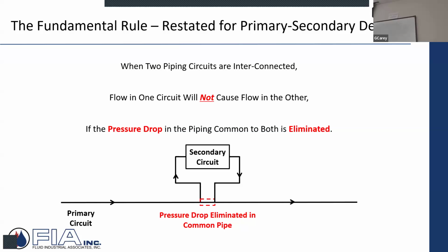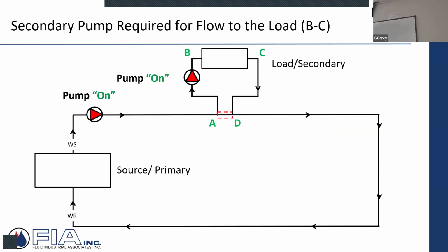Is there a difference? Absolutely. Is it insignificant? Absolutely. So you got this pump flowing along and it will not go through that secondary circuit. And then what would happen is you'd have a secondary pump, so those were the booster pumps that he added to the 10 buildings. And that was the beginning of primary-secondary that you guys design, your firms design. It's used all the time with chillers, boilers, radiant heat, and all of that.